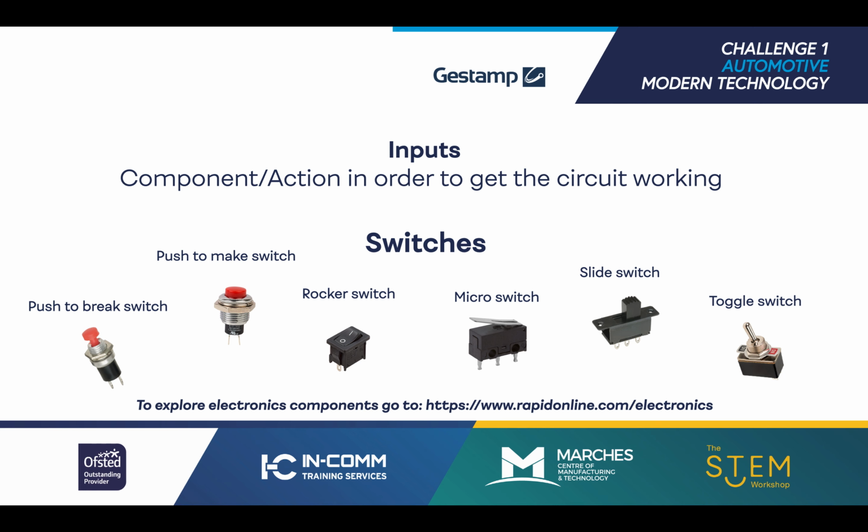If you were designing a system to be embedded into a car, you would design your own casing for a switch maybe, or buy one that exists. But what you do need to consider is how that switch might function. So just running through a couple of these switches, a push to break switch means that the circuit will work unless you push the switch. So the action of holding your finger down on a switch will stop the circuit from working.